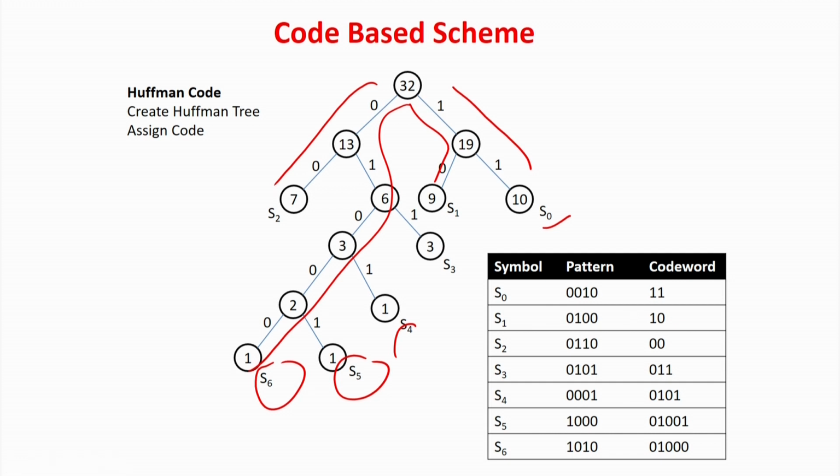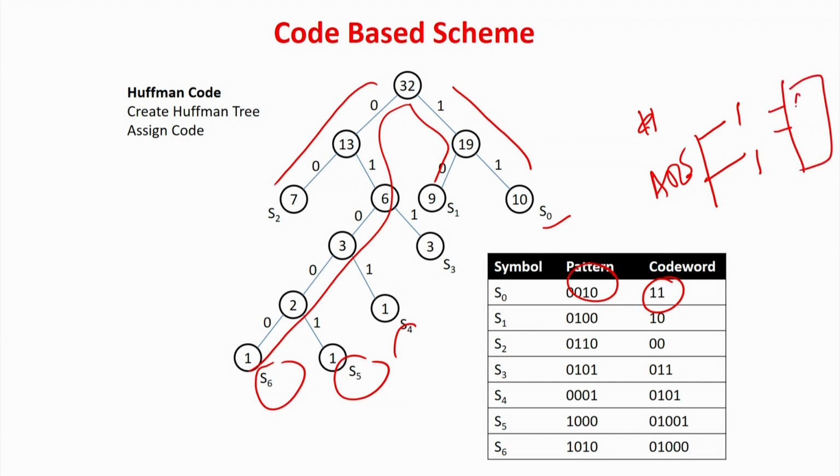But of course, it is very important that when I get this as 1, 1, the decompressor circuit should generate the pattern inside. So maybe 1, 1 will go from the ATE. So ATE will generate 1, 1, with 2 pins there, which I am using for the timing, and it will go to your CUT. So the CUT will be getting 1, 1. Inside there should be a circuit for decompressing it. It will generate it as 0, 0, 1, 0. So there should be decoding circuitry for the Huffman codes, which is a very standard circuit you can study from any textbook. So in this case also 1, 0 and 1, 0, 1 will be there.